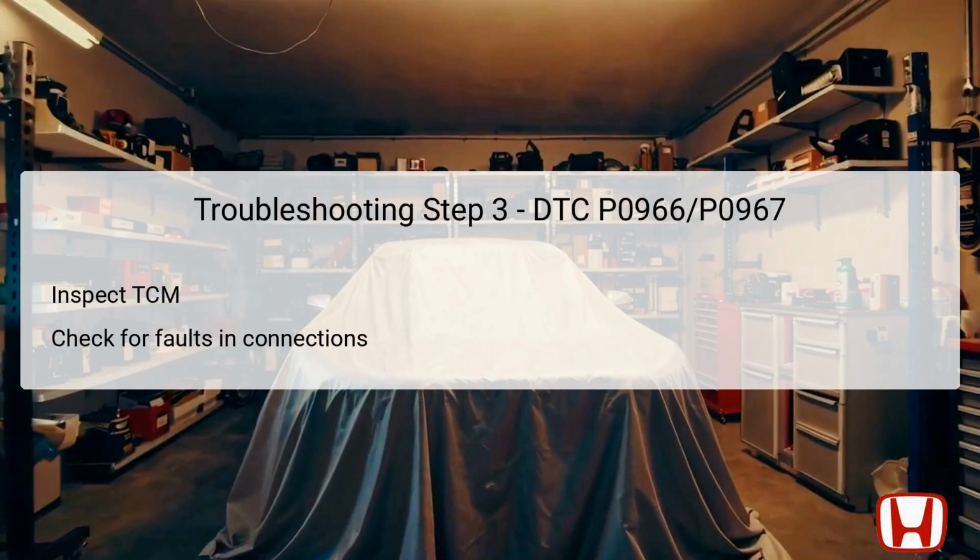After inspecting the external circuit, the next step is to perform a thorough inspection of the TCM itself. This involves checking for any fault codes present that may provide insight into the current malfunction. It's essential to address the TCM by checking its connections and harnesses to ensure a solid connection.